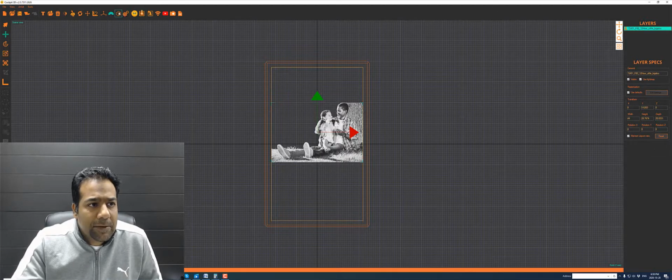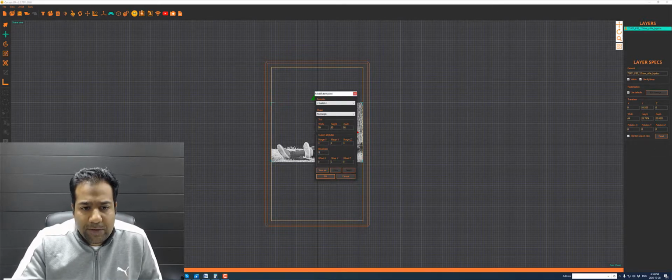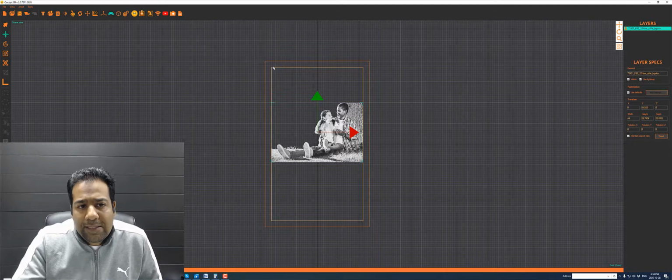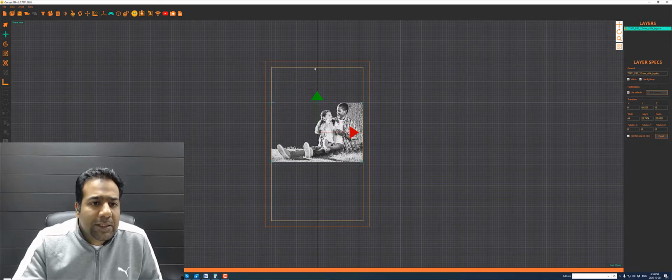Margins are just for safety, right? So let's say, for example, here. Let me just make my bevel 0. So this space from the actual edge of the crystal to the safety margin, I don't want my image to go beyond that safety margin, because I don't want my laser to then come close to the surface. Otherwise, it might crack the crystal. So we create the safety margin.